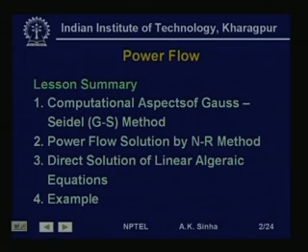In this lesson we will start with some computational aspects of the Gauss-Seidel method. Then we will talk about power flow solution by the Newton-Raphson method. We will then talk about direct solution of linear algebraic equations, as we will find that the Newton-Raphson method finally boils down to solving a set of linear algebraic equations, and then we will take a small example of solving this linear algebraic equation by the Gauss elimination method.